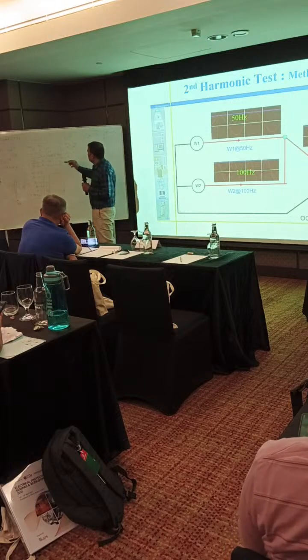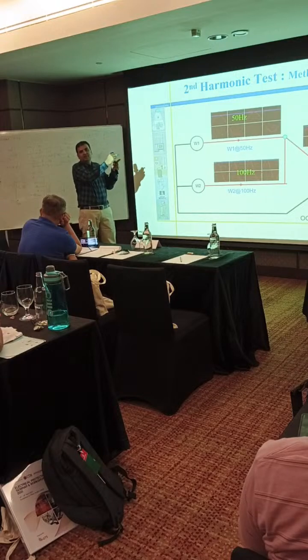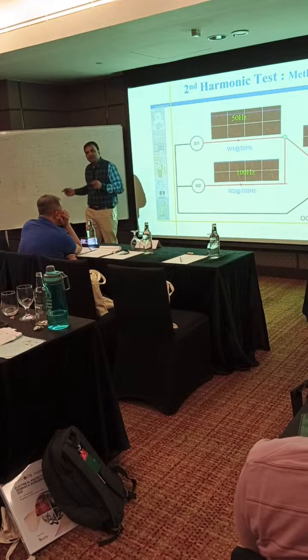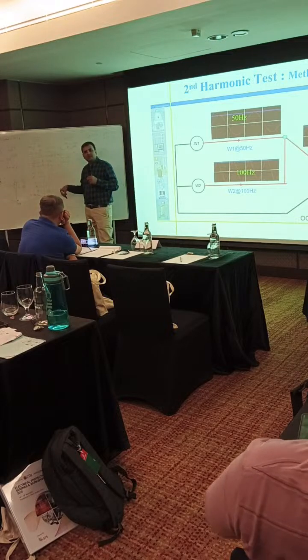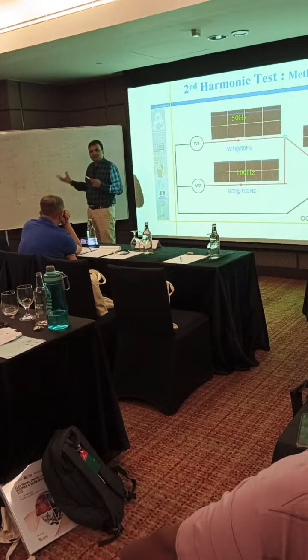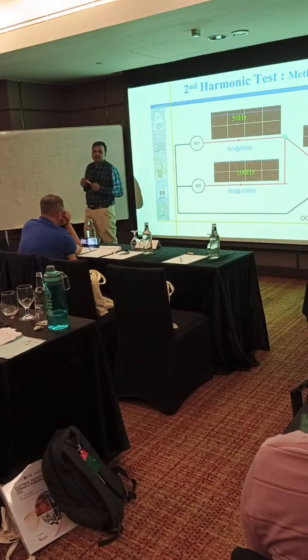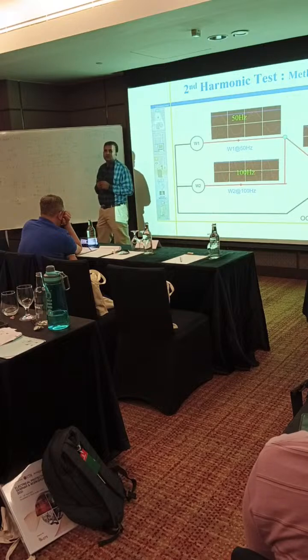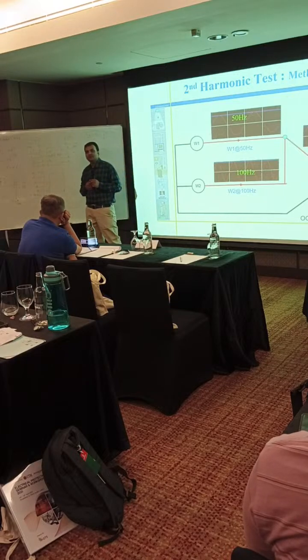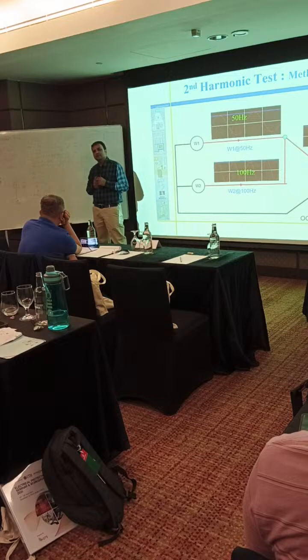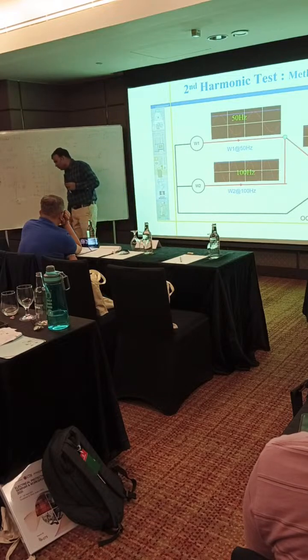So actually it is calculated here in the coil. I have shown you the diagram. Ultimately current is going to the operating coil. The fundamental current is also going there because it is all differential current. The fundamental frequency component the operating coil gets now is 0.73, correct?